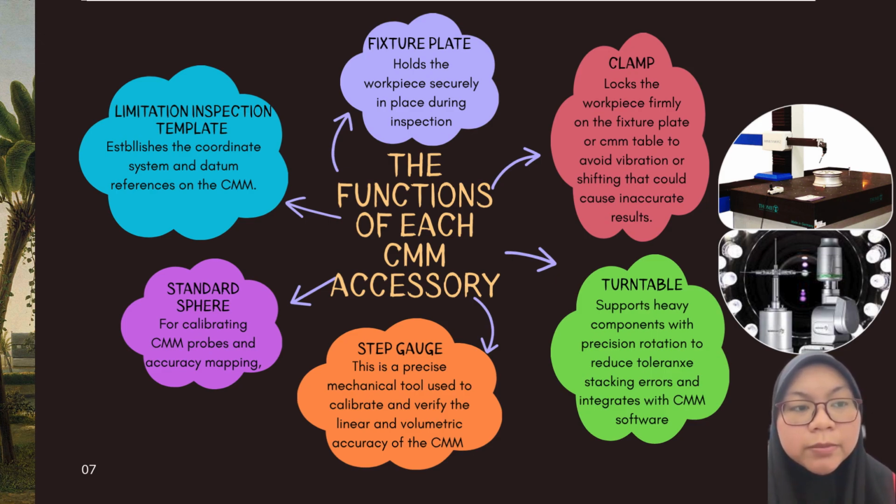The secondary datum B is from the side edge rotation, and the third is tertiary datum C, which is from the location hole for origin setting. It supports balloon drawing and automated reporting, and also improves inspection accuracy and consistency.